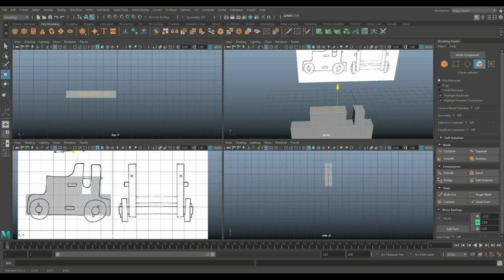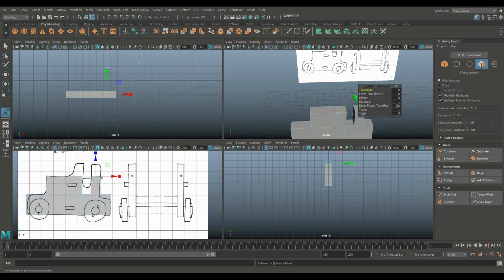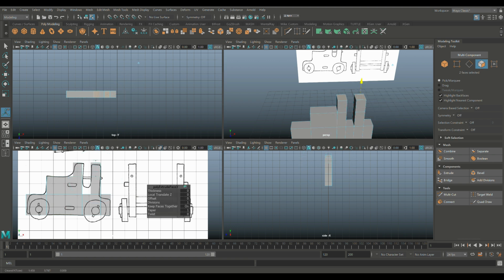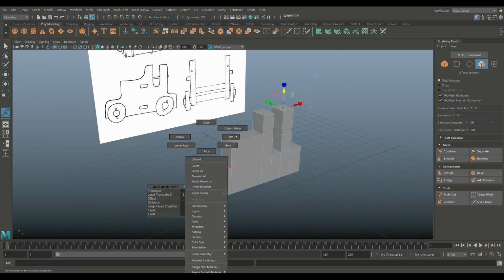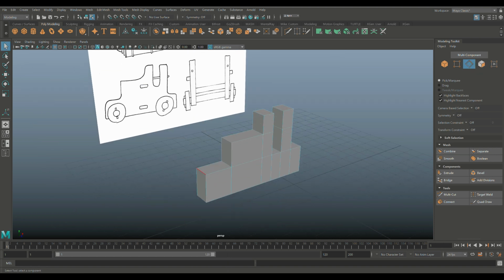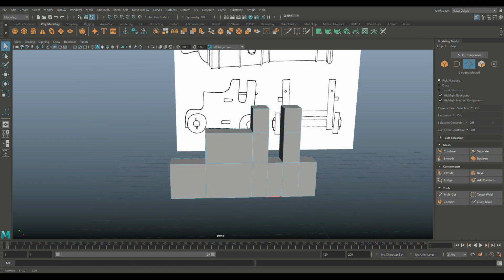That's a bit better, so we'll go that far, and then I'll go in here, right click on the face again, just select that one and that one, Control E and pull that up like so. Right, so we got the basic idea of the shape here. Now from here you can do all sorts of cool things. You can kind of bevel that shape if you like. So we're going to go in here to edge. You can go in and bevel these. Like I said, if you like, you don't have to, but you can.